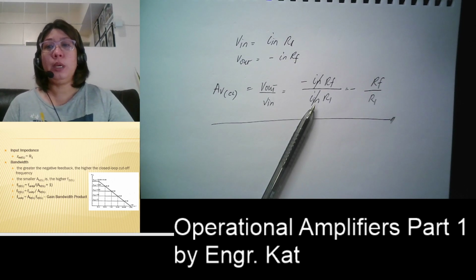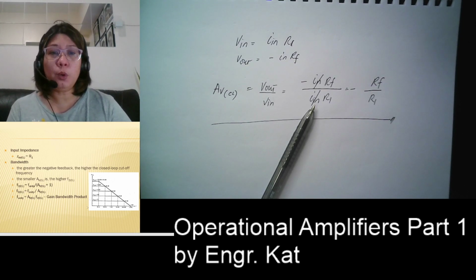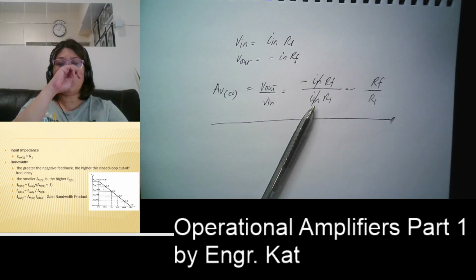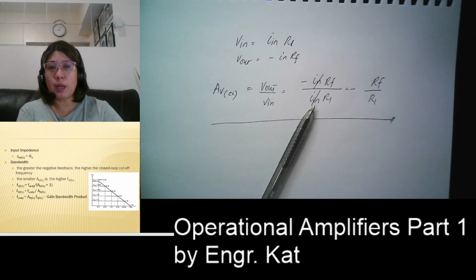Okay, so we have here your F2 or your cutoff frequency. Every time, F1 will start at 0 because this is an operational amplifier. This is directly coupled. Okay, so our question is what will be your upper cutoff frequency? So that is equivalent to